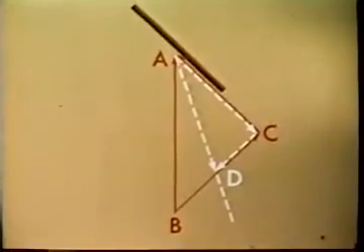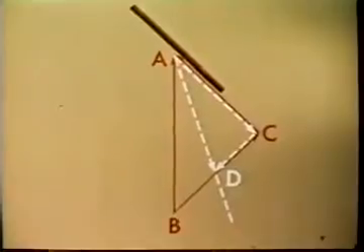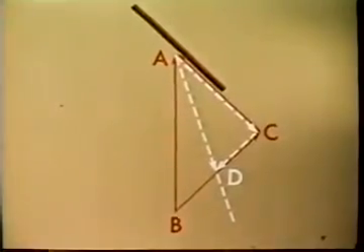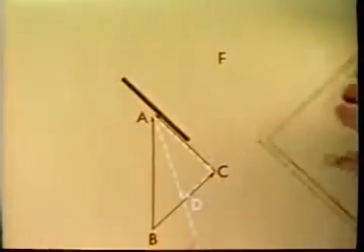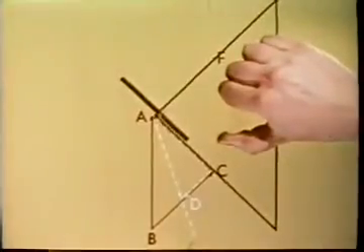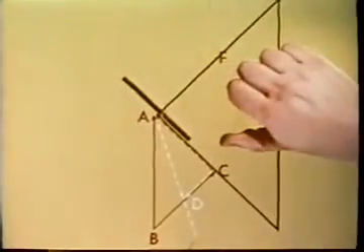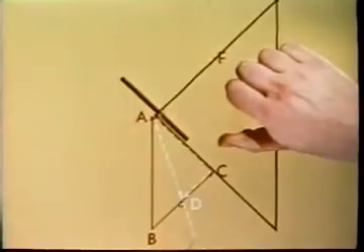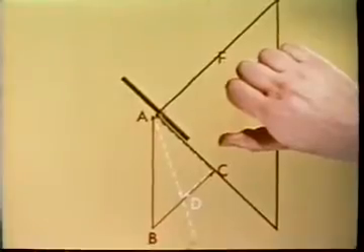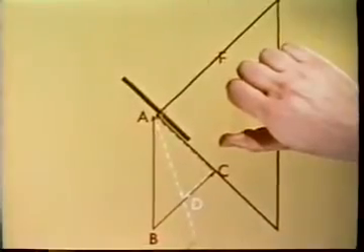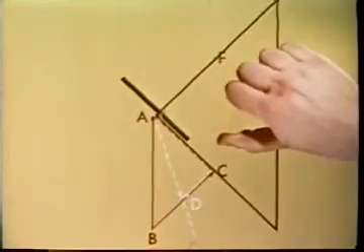To find the largest possible angle of the flight path to the vertical, this geometrical construction can be materialized using a draftsman's square and two drawing pins. The pins are placed at C and a point F situated vertically above C at a distance equal to AB. This square can be moved round so that its two perpendicular edges are in contact with the pins.